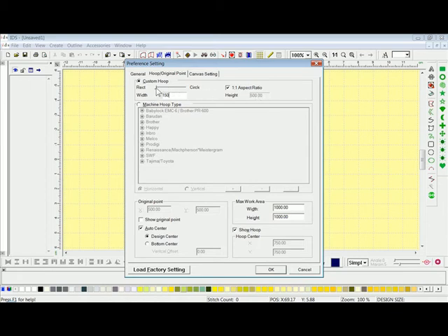There's a bar up here between rectangle and circle, and what that bar is, that changes the corner percentage. You'll notice that most hoops do not have a 90-degree corner. They mostly have a rounded corner. With your scroll bar between rectangle and circle, it goes from 0% all the way up to 100%, where 100% would be a full circle and rectangle or 90-degree corner would be 0. Most hoops that you do see with rounded corners, it will be at about a 30% or so.